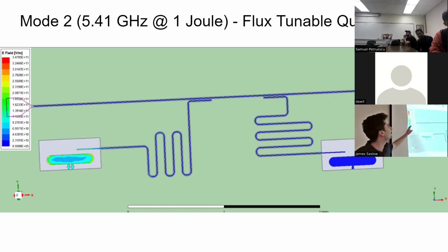So what I'm doing is I'm feeding microwave voltage sources through one of the launch pads at different frequencies. So I'm sweeping through all these frequencies, and then there are these special frequencies that happen at these certain modes. So for example, at 5.41, I see a bunch of electromagnetic activity in one area, but not really so much in the rest. And you can kind of see in the chart that the magnitudes vary.